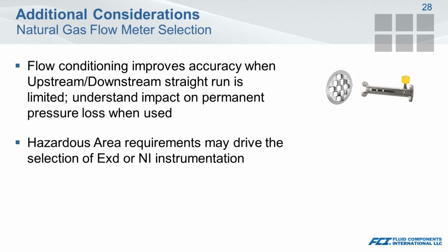Site-specific requirements might be in place for hazardous areas, so we have to look at selection of explosion-proof or non-incendive instrumentation to meet the needs of the site. And a lot of that is going to be backed up by third-party certifications. You'll see this with your manufacturers.